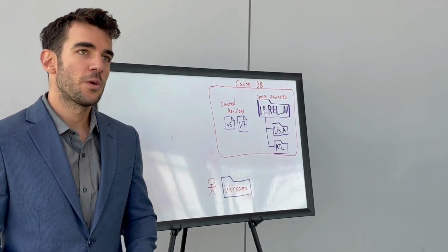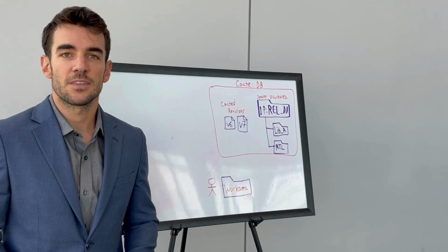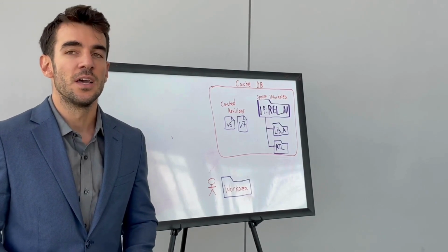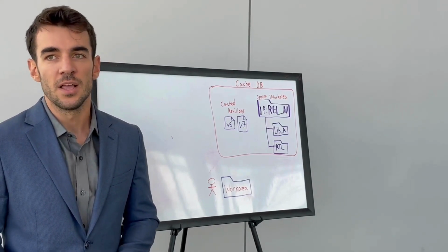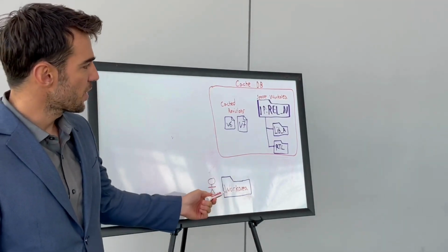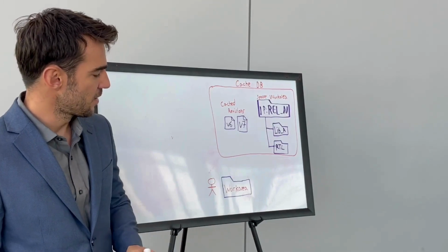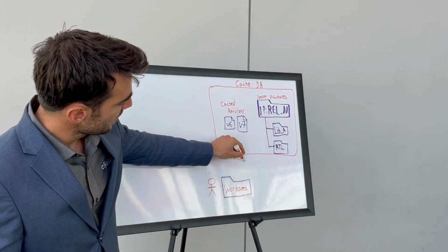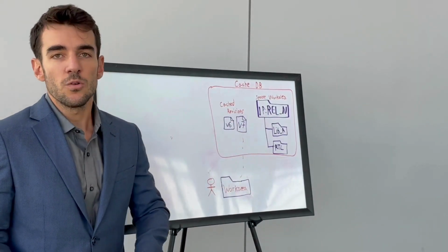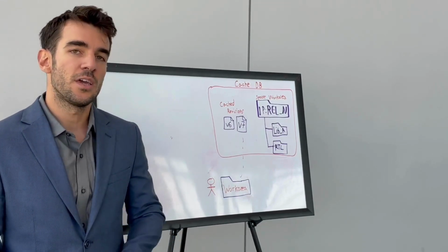Now, what we have seen across almost 2 decades is that we can take advantage of the fact that the data doesn't need to be modifiable in each user's work area, and we have developed a links-to-cache approach. So we have the user's work area and our cache database, where each file in the work area is a link to the cache where the actual data is physically present, and only when a user wants to modify something, they check it out so they get a physical copy in their work area.